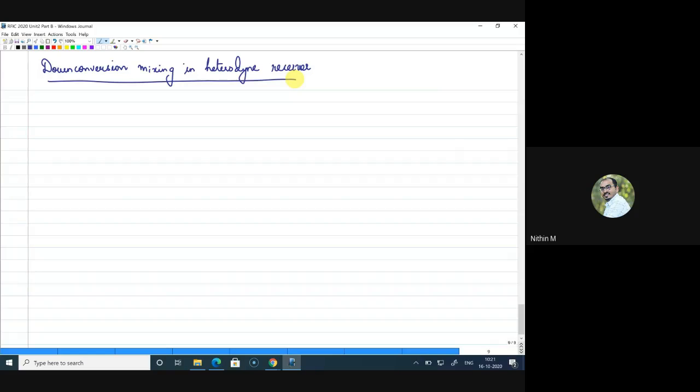One more thing to keep in mind is that the input coming at the mixer is soon after your low noise amplifier, and before that you will have a band select filter. So the input to the mixer itself is a band, so always we should have that understanding. Since it is a band, it will have many channels. For a particular wireless standard, if a receiver is receiving a band, each band will have many channels depending on what wireless standard it is.